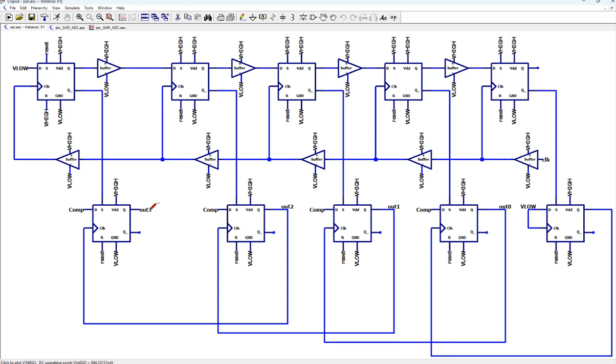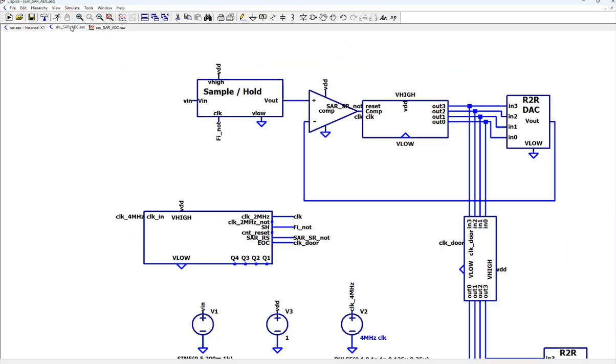And then keep doing that. So you'll have A3, A2, A1, and A0 being available at the outputs. That's 4 clock cycles of the sequencer. And then the fifth one it resets. So you're done with the conversion, right? What's next? What should follow that? Whenever A0 is registered, all A0 to A3 are registered, and they're available over here already.